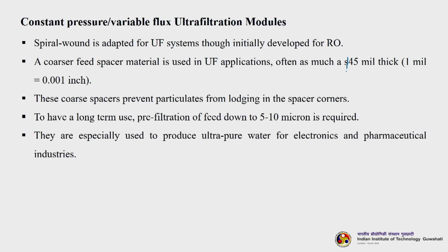1 mil is equal to 0.001 inch. This unit is usually used when we are talking about spacer materials. These coarse spacers prevent particulates from lodging in the spacer corners. To have long term use, pre-filtration of the feed down to 5 to 10 microns is usually required so that the clogging will be less, and they are especially used to produce ultra pure water for electronics as well as pharmaceutical industries.